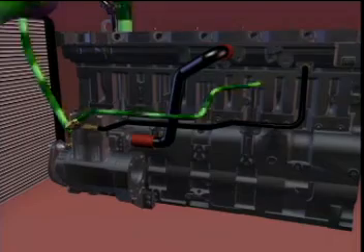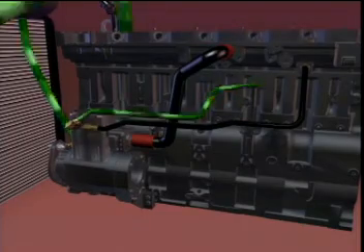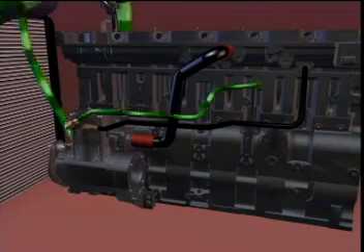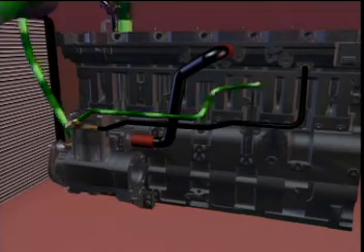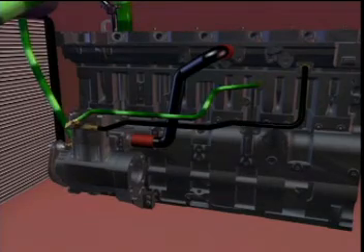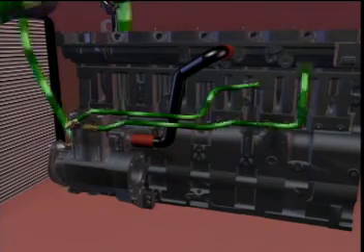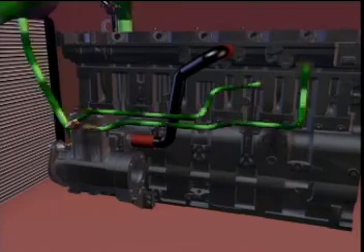The air compressor receives coolant through a line connected to a fitting in the cylinder block near cylinder number 5. Coolant travels to the air compressor cylinder head to cool the compressor. From the compressor, an external line directs the coolant back to the engine cylinder head.